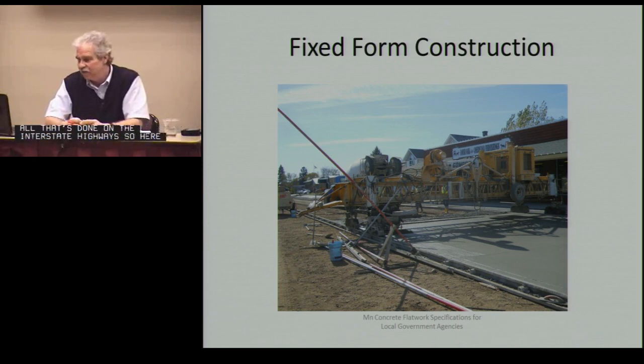But this one, they did the regular testing rate of every 100 cubic yards and everything that's done on a state highway. And the testing costs got the city council a little upset. We had to pay all this extra money. We thought concrete was this much more, and then it was this much more. So this way, most of these costs would be included in the bid. When they go to alternate bids, the testing costs will be there, and the cities will know what it is. They won't get surprised at the end of the project from their local engineer. So that's, again, kind of the genesis and what started the specification.